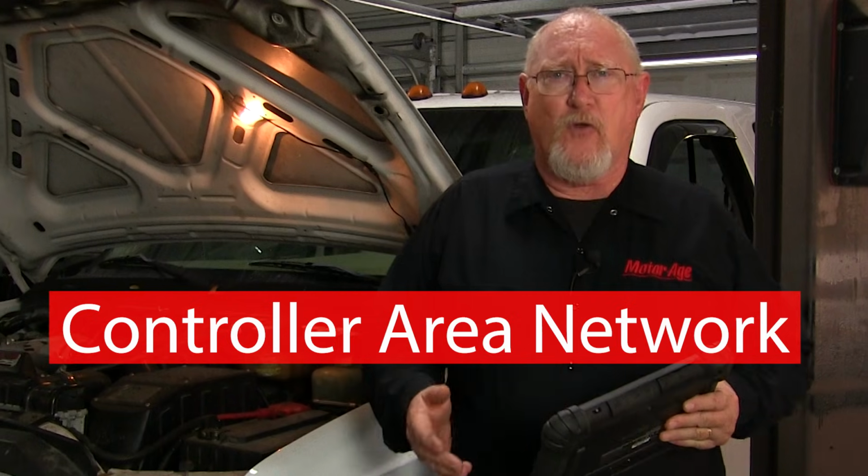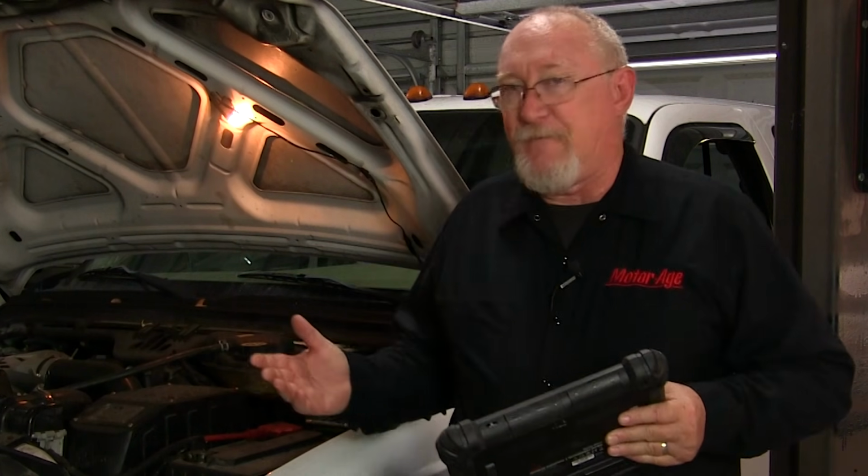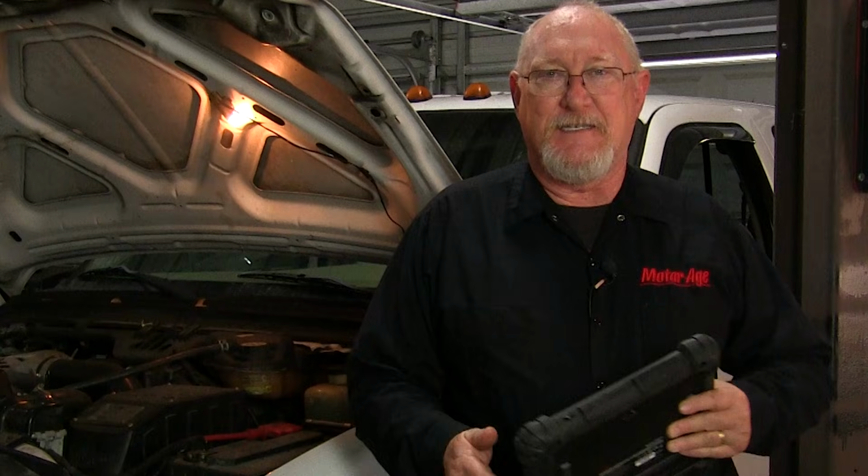That stands for Controller Area Network, and many late model vehicles may have 3 different CAN networks on them, operating at different speeds, which means how fast they're able to transmit data from one module to another. Now in the case of the F350, there's only the one CAN network, and because it's tied to the powertrain, this data needs to be transferred right here, right now, and it uses CAN C, the fastest of the 3.